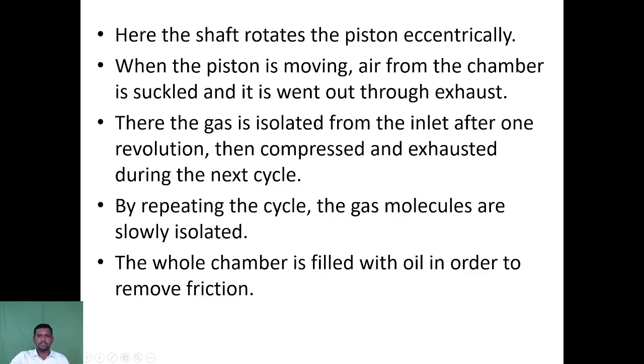Here the gas is isolated from the inlet after one revolution, then compressed, and then exhausted during the next cycle. So this cycle is continuously repeated, and the gas molecules are slowly isolated in order to achieve vacuum. Here the whole chamber is filled with oil in order to remove friction.